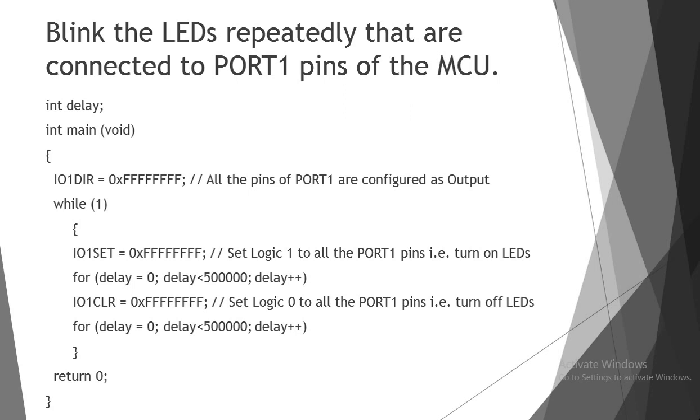So we will write IO1DIR = 0xFF. So it will be configured as an output port. Now we are generating one infinite loop. In this loop we are setting all the pins and then we will reset them.